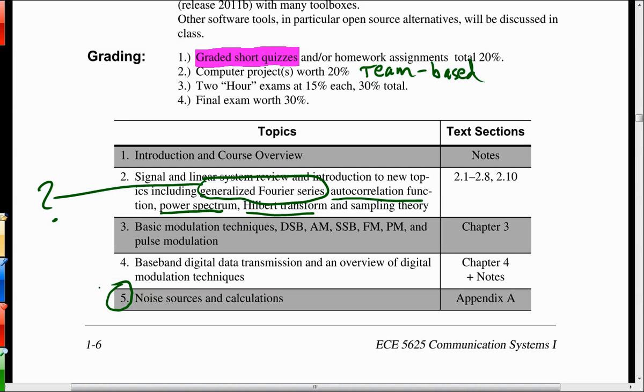This is more of a physical thing, but it's something that hampers all communication systems, and that is noise. Noise is actually modeled probabilistically using random processes and random variables. But the modeling of it, say the excess noise across the terminals of a resistor when it's at room temperature, that's the type of modeling, so you can understand noise figure and a link budget for a system.